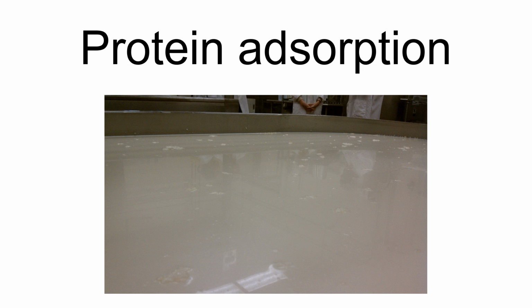Also, proteins stuck to the heater may cause a burnt taste or color in the bulk material. Additionally, in processes that employ filtration, protein aggregates that gather on the surface of the filter can block the flow of the bulk material and greatly reduce filter efficiency.